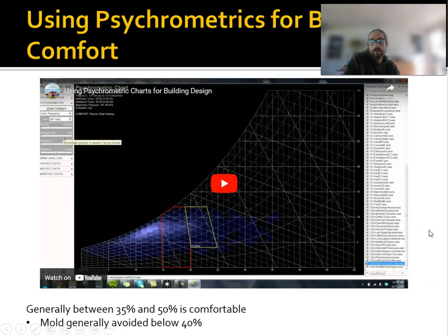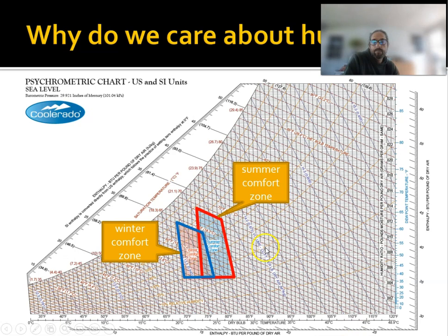And there's a video that's posted, so make sure you watch that. But there are these recognized comfort zones. Generally between 35 and 50% relative humidity is comfortable. Somewhere around, we'll call it 65 to 75 degrees. It depends on who you ask, but that's your comfort zone. Not everybody falls into this, but this is a general rule of thumb. Like if you're in here in the winter, you're okay. If you're in this area in the summer, you're okay. And we'll investigate that more in a lab.